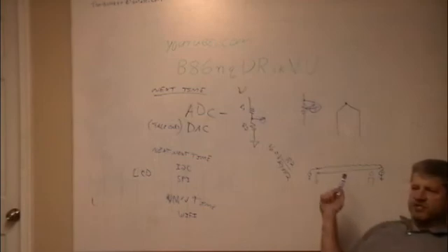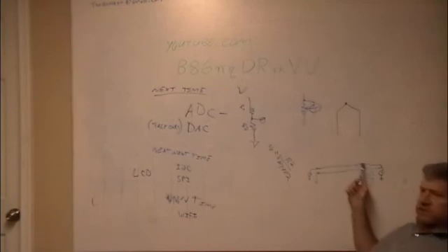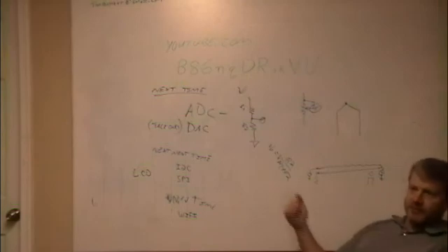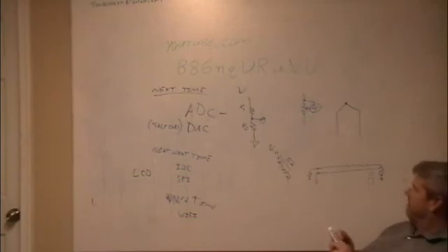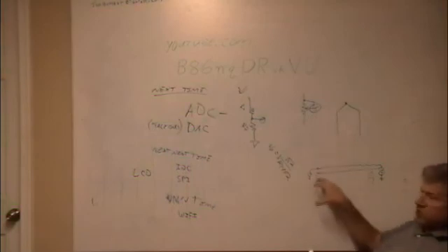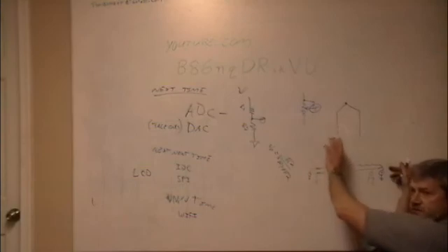But that's the difference between a J, a K, an L? No, you skip L. There are 4 basic types of thermocouples, and what they are is different metals. If you're doing a really hot temperature process, you'll melt your copper, so you use a different one. And 90% of it is that. But what happens is, as my room temperature changes, I'm changing the temperature end to end.